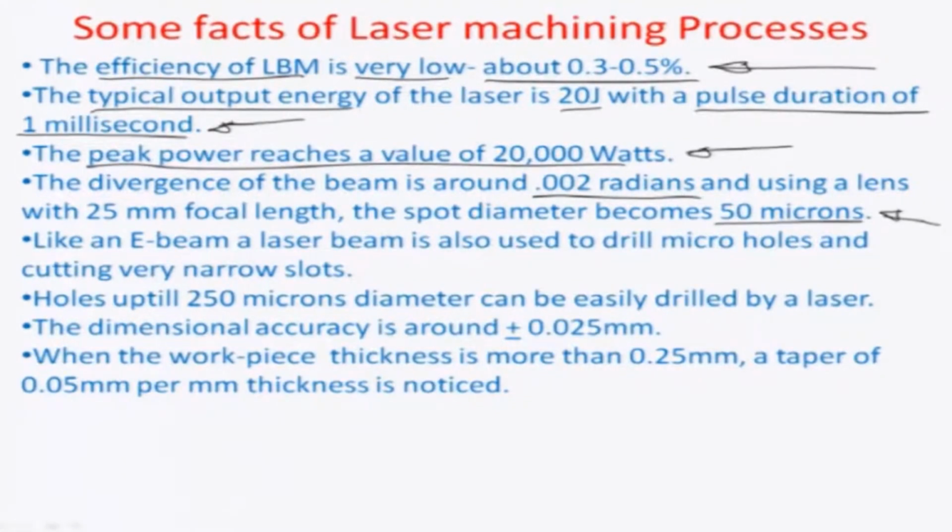These days, the limit has been pushed in the case of laser lithography systems to close to 2 to 3 microns, and that is how low you can get this spot size to be, with the optical technology getting developed in parallel.